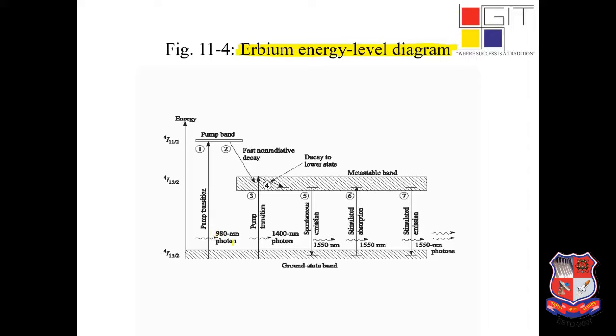So 980 nanometer waves are coming in, and it induces, the word over here is induces, because as you can see, it's a spontaneous or a stimulated transmission. It might not happen naturally, but it might even be forced. So you have light coming in at 980 nanometers, and the output that you're getting is at 1550 nanometers, but the output is further amplified in energy.